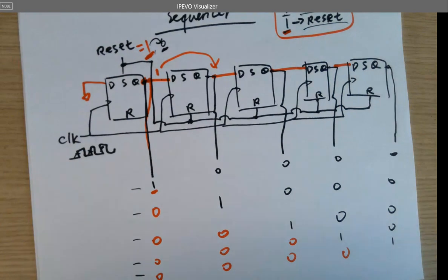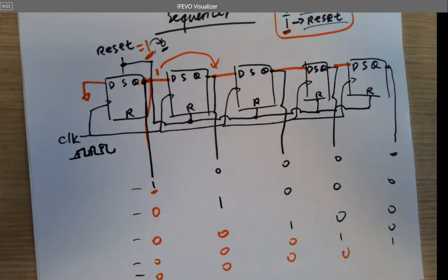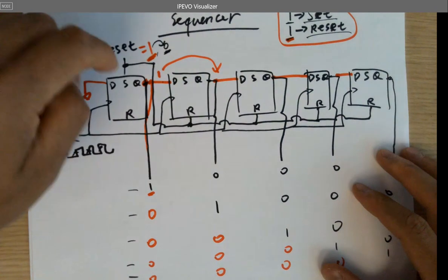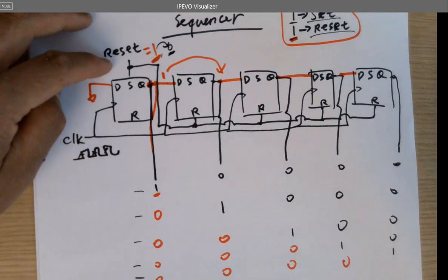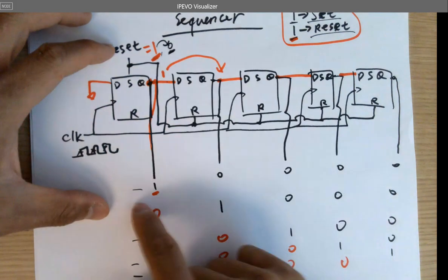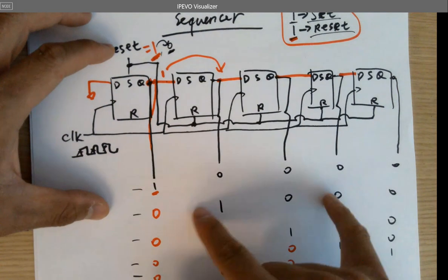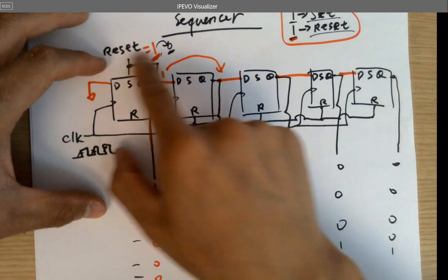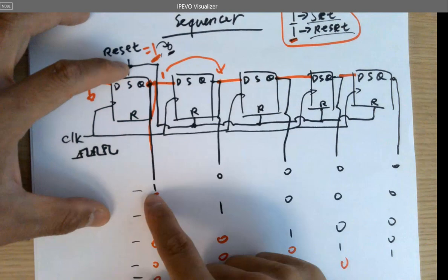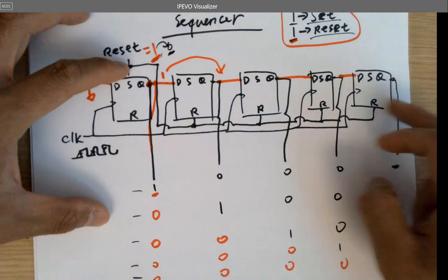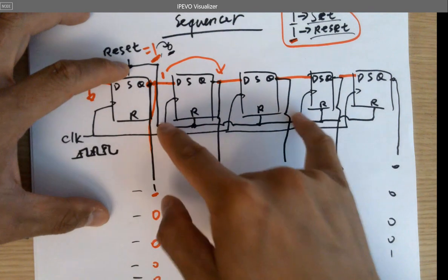So the way that works is at the very beginning, whenever it's ready to do the conversion, what's going to happen is the very first step is to reset it, to reset the start logic. Okay, you put a 1 here. No matter what the output here used to be, doesn't matter. Okay, now let's start a new conversion. Then put a 1 here. What's going to happen? It's going to force the output, the Qs of these.